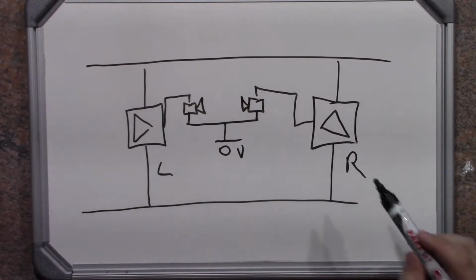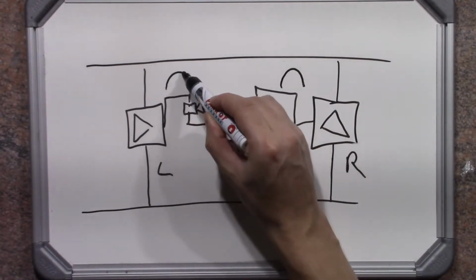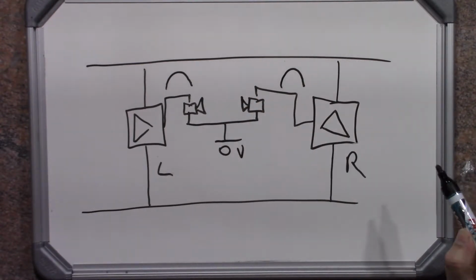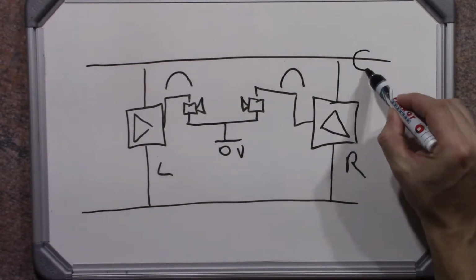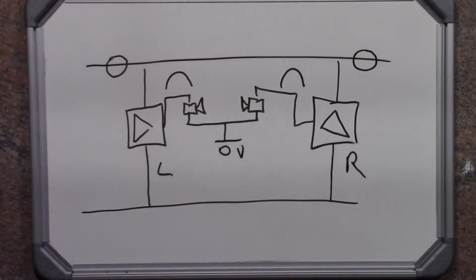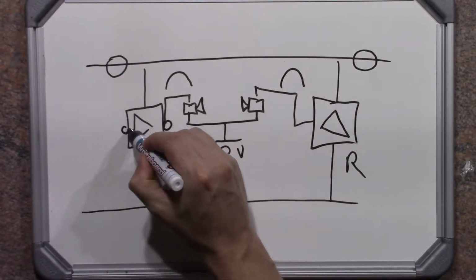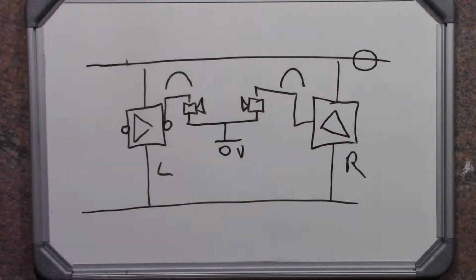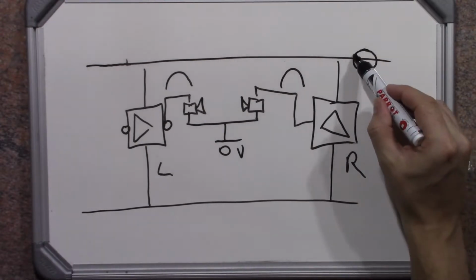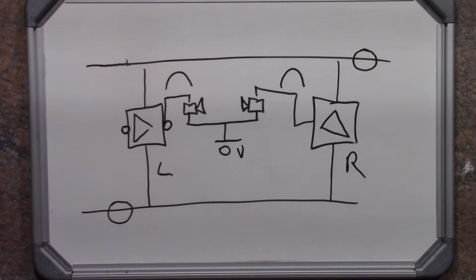So if the two are in phase and you're producing positive current over here, you're producing positive current here at the same time, which means you're drawing lots of current out of this supply at the same time. So instead of doing that, we invert the output and we invert the input of one channel. Now you'll be drawing current out of here and you'll be drawing current out of here. This simply reduces the amount of current that the capacitors need to produce at an instance in time.